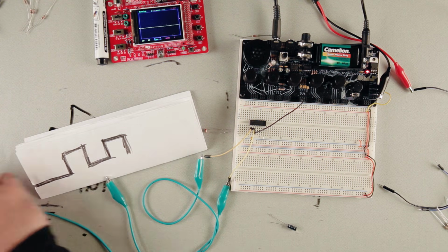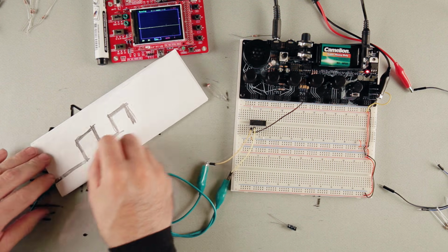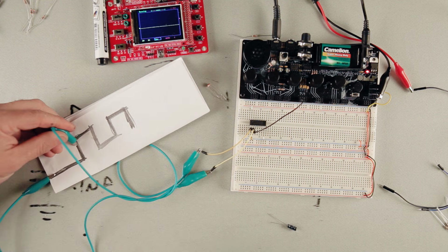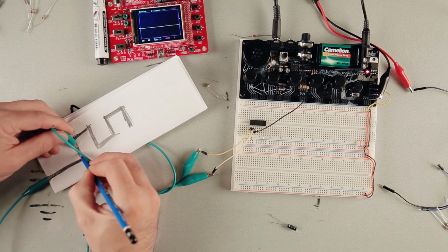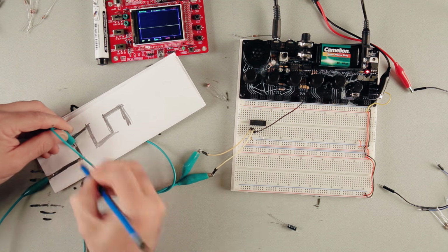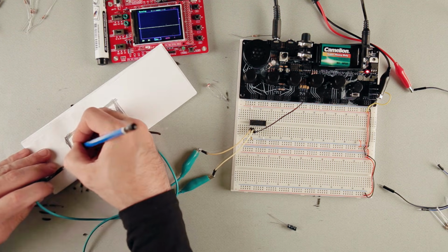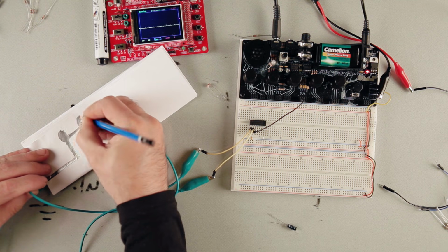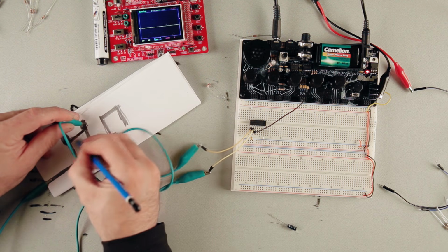And the more graphite there is, the less resistance there will be. So, which I'll show you. So, and that goes down pretty fast. But maybe I want, so at this point, but as I put more graphite, you're going to hear the pitch go up. So you can really tune it to be at different notes. If you want it to be different notes, you can just sort of add more graphite until it gets to the note that you want. So that jump is too big, so I'm going to add a little more.